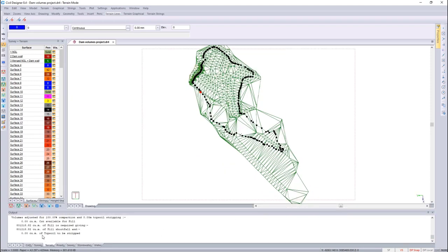Okay, just to view that result. So 801218. So pretty close to our 801,000 that we got with the dam volumes on the flood volumes. You could probably make that depth increment a little bit smaller and come up with a slightly more accurate result, but within that 801, close to 801,000, I think we're pretty close to what we're looking for.